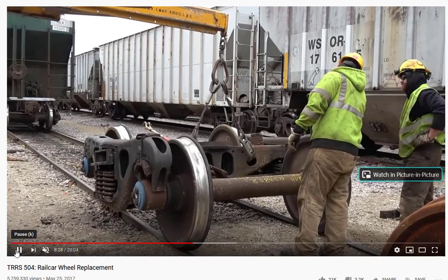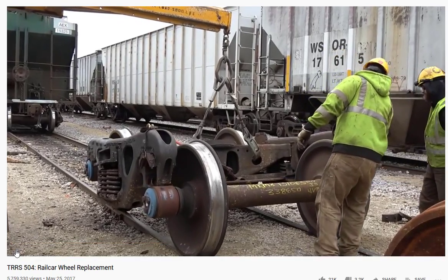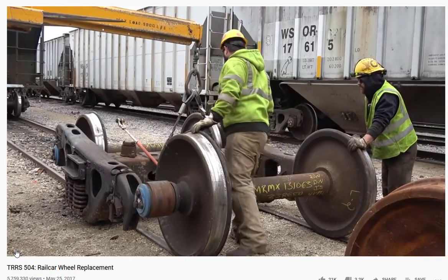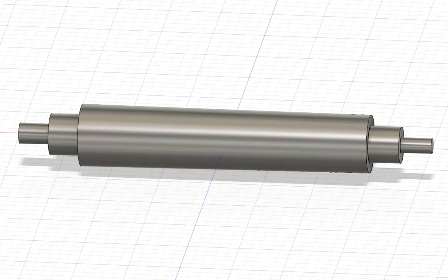This video gives you some notion of what it takes to replace the wheels and axle on a rail car. We can easily imagine coming up with a model of the axle and the wheels, and we can separate the axle from the wheels and take a look at how we expect that axle to be loaded when the train is in service. I added some extra step on this particular shaft that may not be there in the train shaft, but the important thing is that we have the bearings on the outside here and there that we will have load pushing down on those.